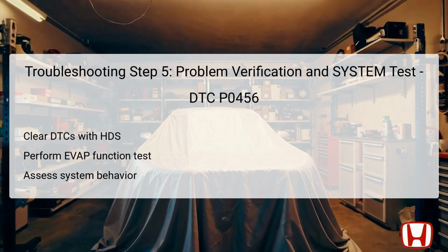In this verification step, turn the ignition to on and use Honda's HDS diagnostic tool to clear existing DTC P0456. Then, run the EVAP system function test via the HDS inspection menu. The goal is to see if the system passes the test without errors.